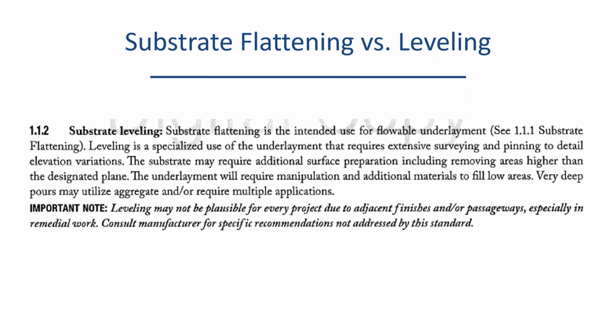It may require some different prep. It may require a more aggressive CSP. It's a different animal if you want it perfectly level. It can be done, but it's far more time consuming, and the contractor really has to have a lot of experience in getting it perfectly level and know exactly where the irregularities are on the floor. So quite often there's little tabs, pins that they put out, and they have different heights to them. Where it's out, where it's deep, they'll have a deeper pin, and in another area they might have one that's not quite as deep.